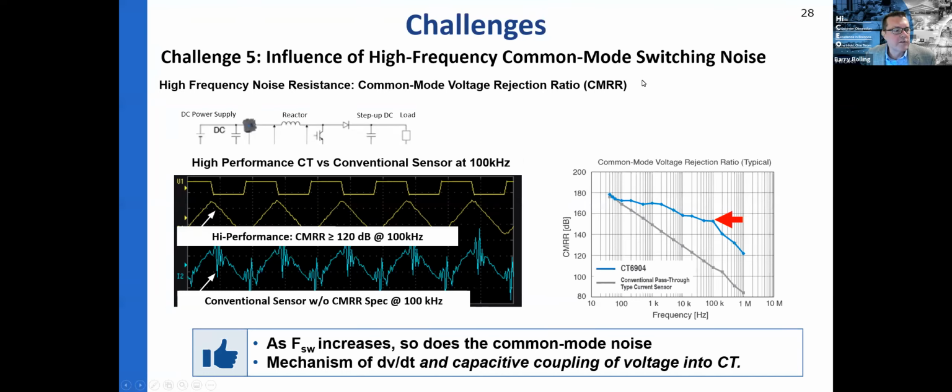The reason was current transducers weren't faced with these rise times. This is the enemy here. It's not the switching rate, it's the rise time and the fall time. And here's just an example. We've got a CT here, and we're making a voltage and a current measurement. Here U1 is the voltage waveform from that step up converter in that schematic, and then here's ideally the current waveform.